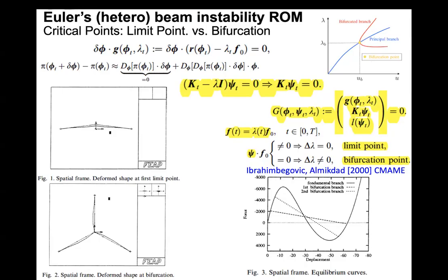And so basically the first one is computed when you're getting the limit of your lambda, so L would be just the norm of this critical mode minus 1, or the bifurcation mode is computed when the critical mode is perpendicular to the loading that you're applying, because you snap out in different things. So it depends what you put here.